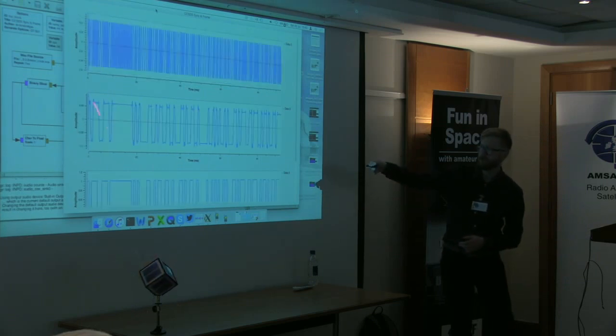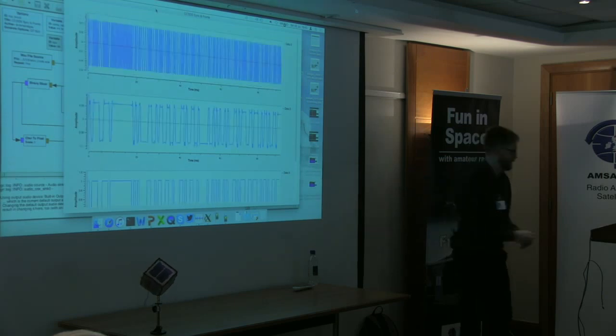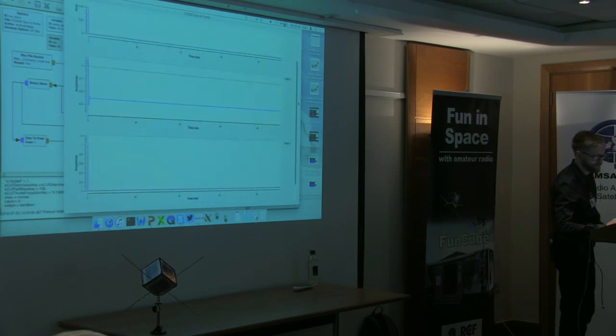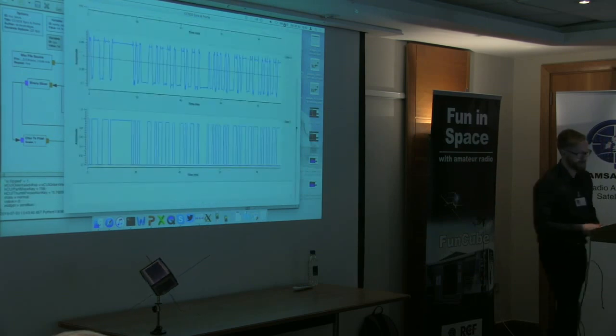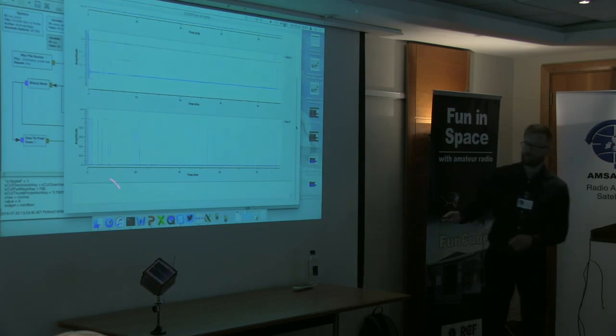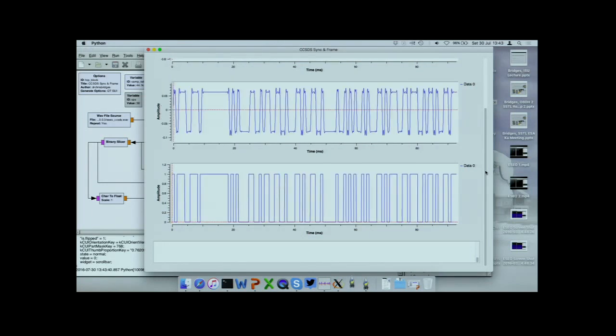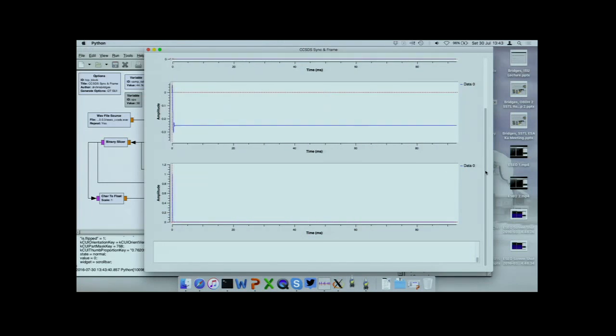We're then trying to measure it using a Hilbert transform to know when the changes are in our system. And if I scroll down a bit further, you can see our noughts and ones, and just a bit further again, I then chucked it out as ASCII at the bottom here. Okay, all using the tags and all the tools that are in GNU Radio with zero programming. This one is just dragging and dropping blocks.